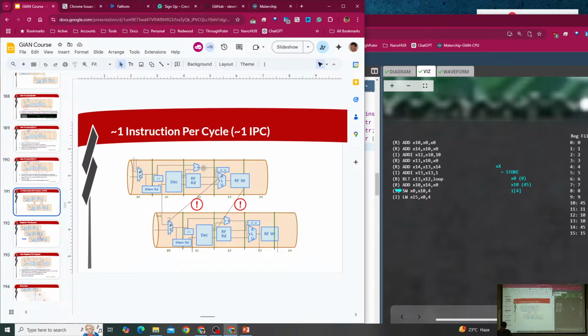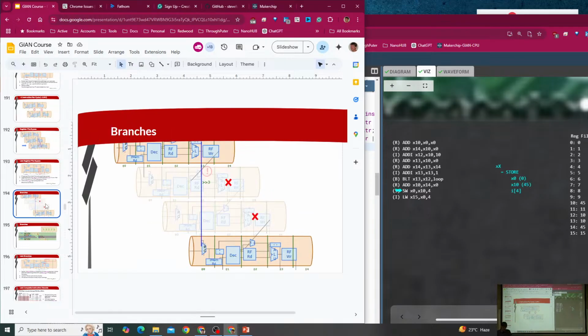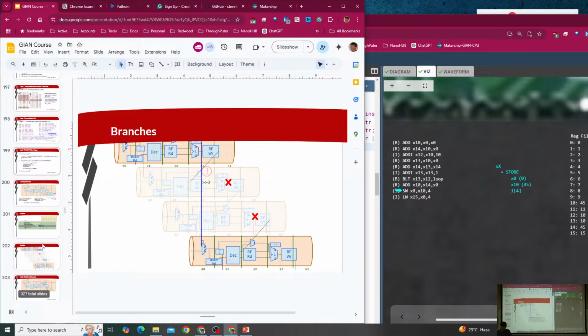Maybe I shouldn't say logic optimization; it's a performance optimization, right? But we'll treat it the same way with a 2-cycle delay to get the target. So we're implementing this picture, right? For jumps, just like branches that are taken, we need to create these 2 dead cycles, the shadow of the jump.